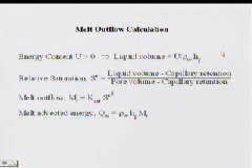Some snowmelt models actually try and keep track of meltwater being generated at the surface and then penetrating through the snow, and they talk about the depth of a wetting front and a kinematic wave process as it penetrates down and drains out the bottom. I wanted to try and avoid having to do that because it's a really complicated process, and I don't think it follows an orderly wetting front type of system. There've been studies done where people have put dye on snow, and they see it's really a fingering type of process.